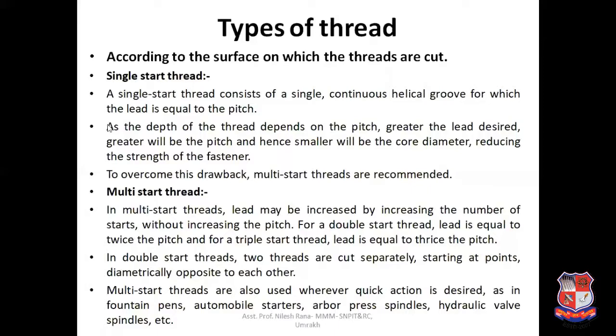As the depth of the thread depends on the pitch, the greater the lead desired, the greater will be the pitch, and hence the smaller will be the core diameter, reducing the strength of the fastener. What it tells is that if you increase the value of the pitch, the lead will increase in a single start thread.